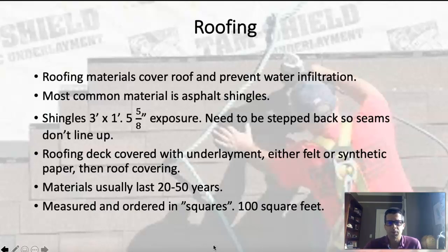With the asphalt shingles, there are different grades of material that you can buy. And usually, if you have the money up front, it makes more sense to buy the 50-year shingle versus the 30-year shingle, because the really expensive part of roofing or anything is the labor involved. So if you buy a 50-year shingle and only have to apply it once, it might make more sense financially in the long run than having to do the roof twice with a 30-year shingle. But some people are going to pay for one roof, and that's all they're ever going to pay for anyway, so it might not really matter.